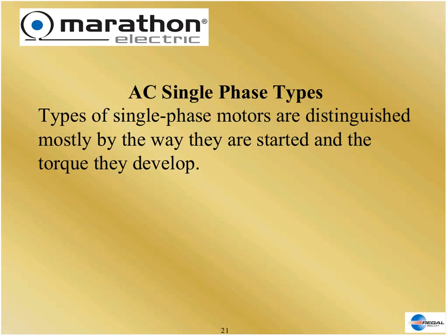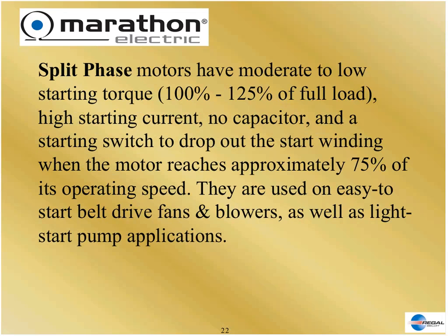Most single-phase motors are not called Design A, B, or C. They're actually named for the way they are started and how much torque they produce. One of the most common is called a split-phase motor. Split-phase motors have moderate starting torque, and the switch is involved in taking the start winding out of the circuit, which we'll see in just a minute. And they are usually used for variable torque loads. Remember, variable torque loads are fans and blowers that are easy to start, so you don't need a lot of starting torque.